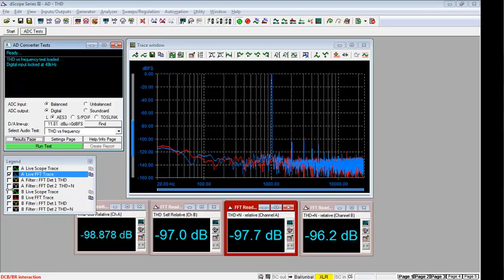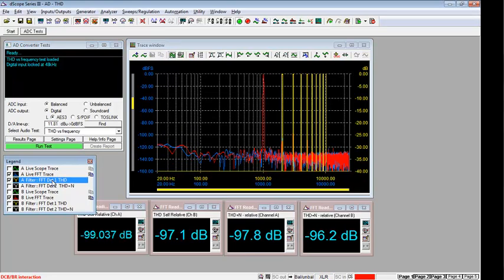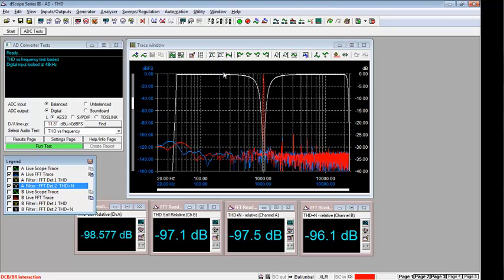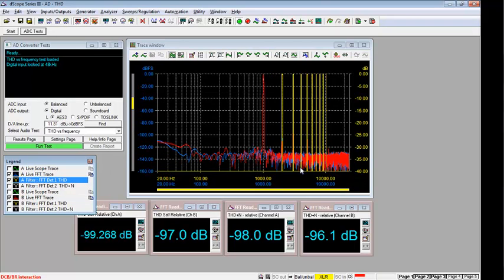Well, that's because I want to isolate the total harmonic distortion from the total harmonic distortion plus noise. And THD plus N is measured using this white filter here. So it's a conventional looking notch filter to remove the fundamental and analyse everything that remains, all the noise and all the distortion. Now, as a designer, we may want to understand whether the THD plus N figure is dominated by noise or by distortion. So what I can do is, at the same time, measure THD only, so total harmonic distortion.